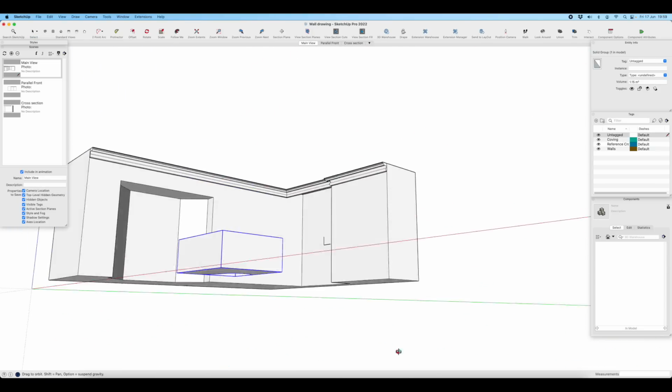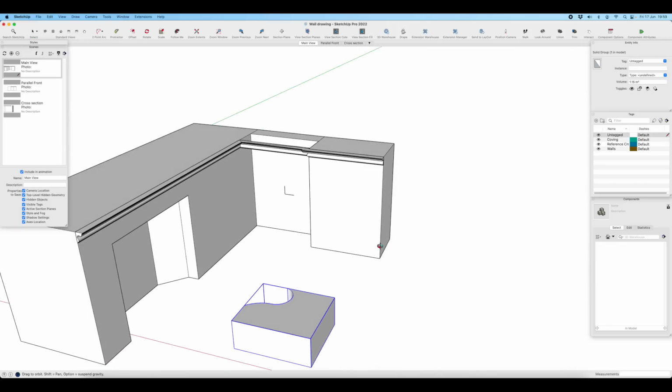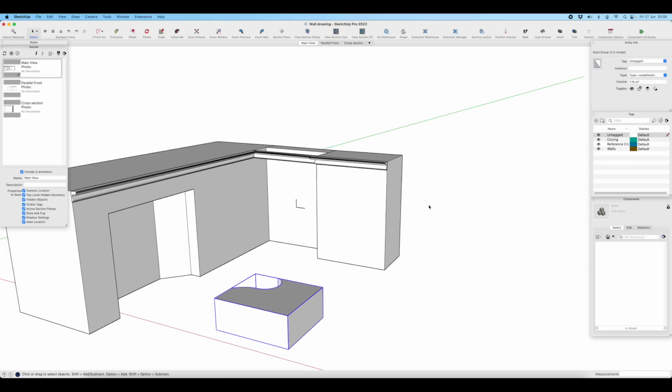If I'm doing a detailed model of a joint or a window, it's really handy to, once you've built your tenon, to put it into the other component, and it will make all the counterpart mortise in the other component just instantly for you. So that's sort of dipping your toe into what solid groups and the solid tools can do.